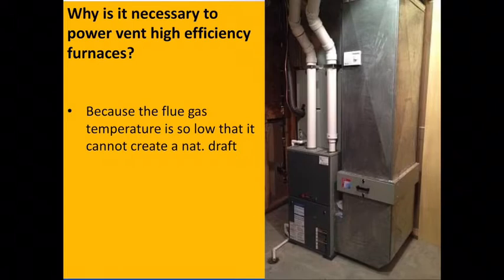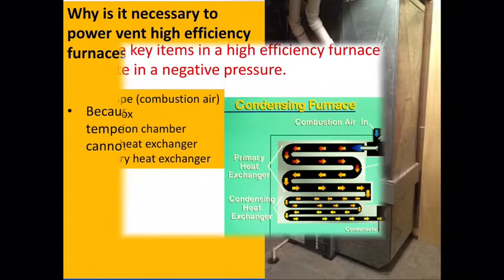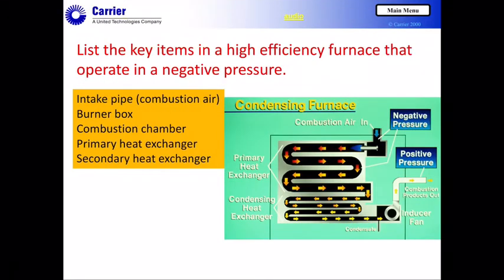In a lot of these cases, especially for a condensing furnace, you might be dealing with flue gas temps that are going to be closer to 110, 120 degrees. So it would not shock me to not have enough energy for that. I've seen them be down as low as 70, 80 degrees if you're running cold enough return temps for return air. So you're not going to get the energy needed to vent these.